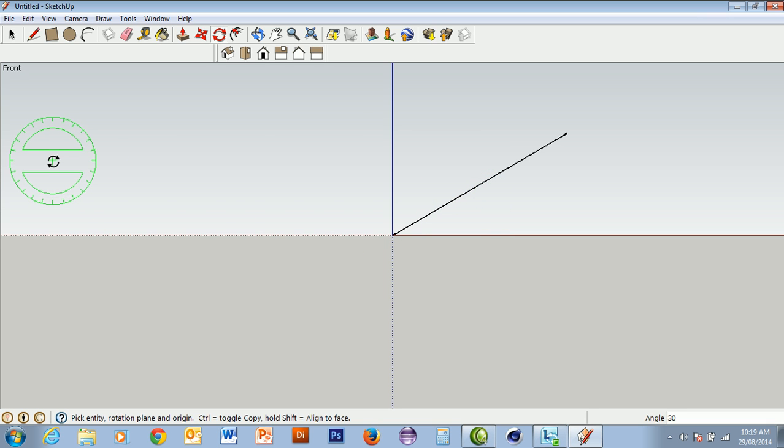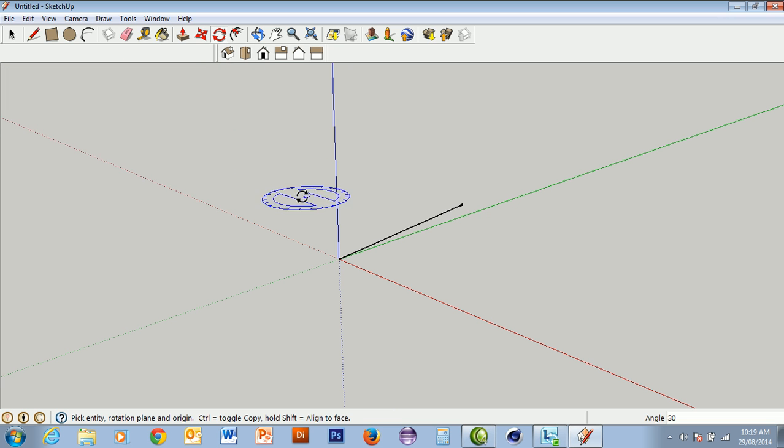And that's a very handy thing when you're trying to do architectural types of work. So there it is, 30 degrees. If you want to just join that back down, you just follow the blue line down to the baseline, back across to the center. You've got yourself a triangle. You know that this is a 30-degree angle here. You know that this is a 90-degree angle here because it's square. And you know then that this will be a 60-degree angle because of the rules of triangles.